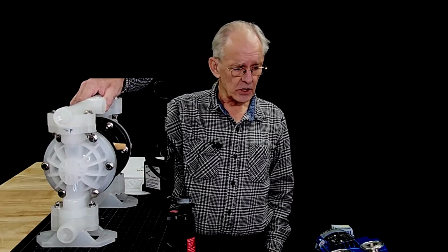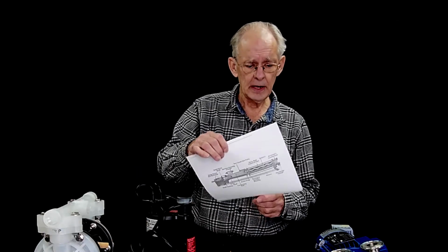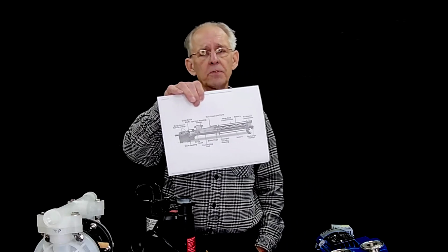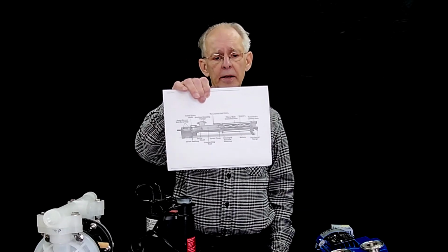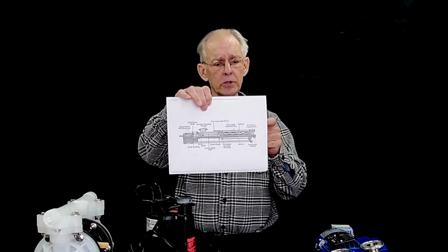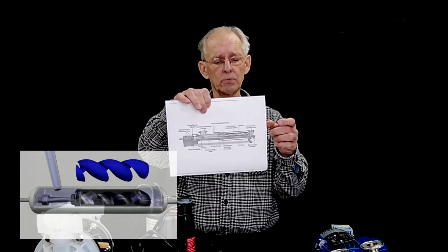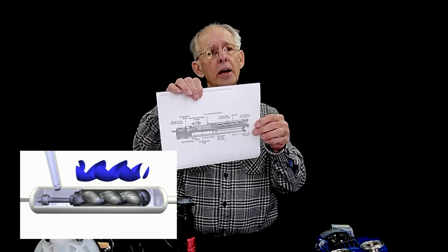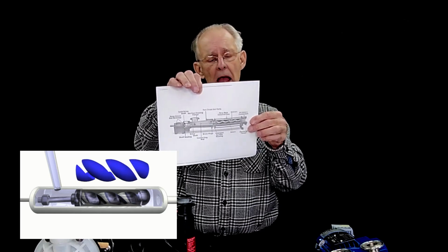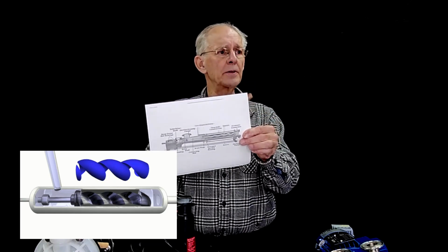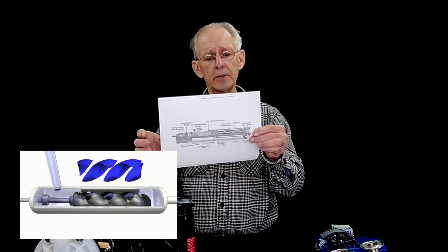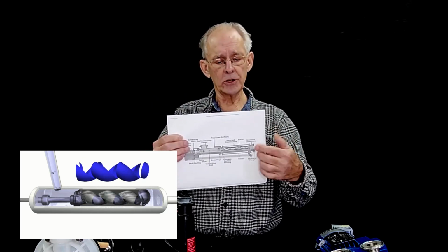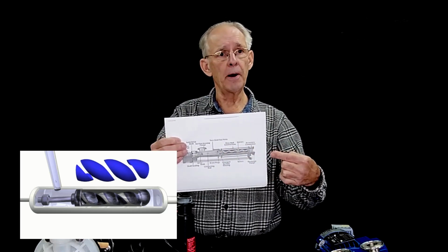Okay? So then we have some other positive displacement pumps. This one is called a progressive cavity pump. And it's kind of strange how it works. There's a stainless rotor, which is like a spiral screw inside of a rubber stator, and the screw kind of walks around in the rubber stator, and that walking action creates cavities that move through the pump.